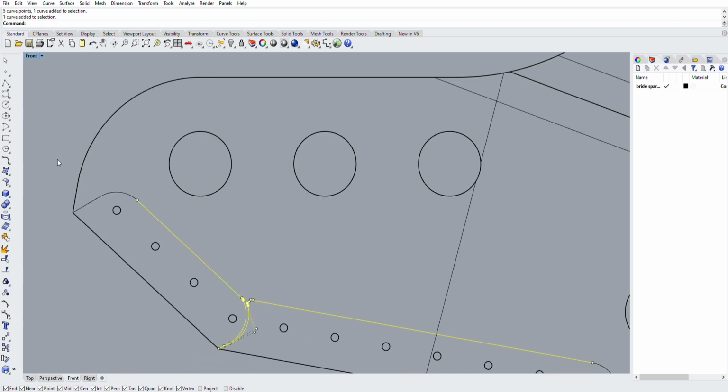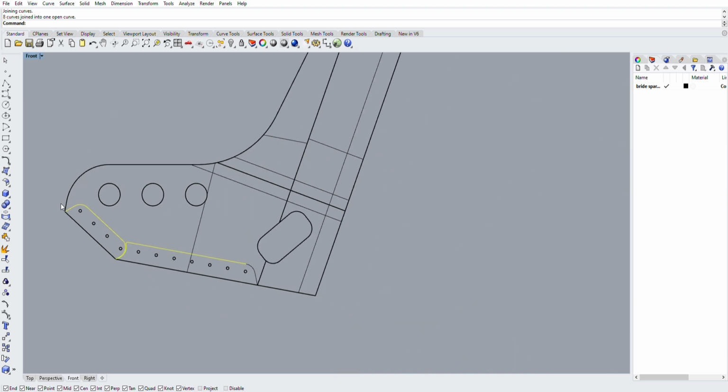And I'm using the back and sides as the overlay because that means I already know that my flanges are going to work for my rivet holes. I've got meat around them because I'm literally staring at it in 3 dimensions here. So I know that they're going to fit.